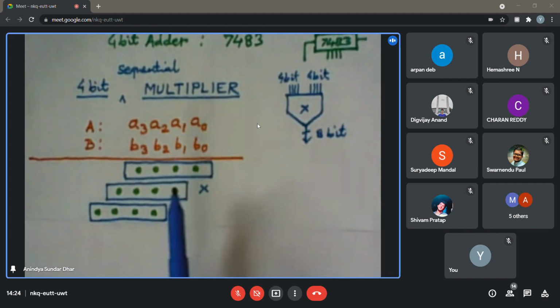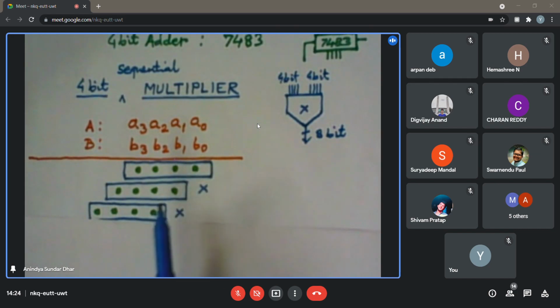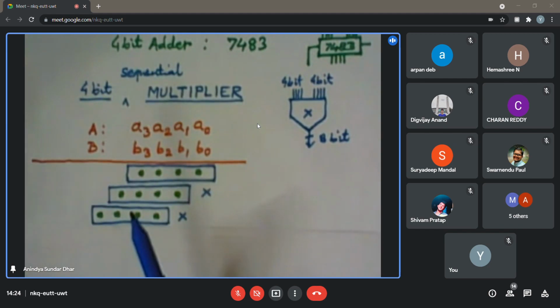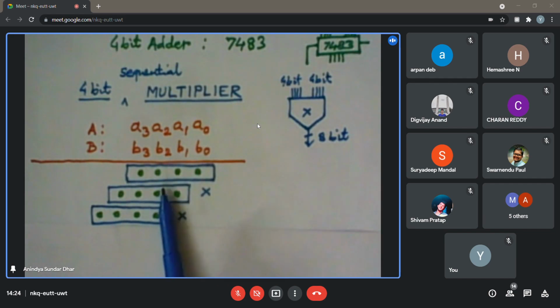Whatever you have suggested, 5-bit, 6-bit, whatever, now I have another 4-bit number which is shifted by 2-bit positions. That means I may assume 2 zeros are there. So I need to add this 4-bit number, a shifted version of that really, with the previously accumulated partial products. I am calling those two I've added the intermediate partial product. So I will be adding this 4-bit number, shifted by 2-bit positions, with that accumulated partial product. So what will be the requirement in this case?